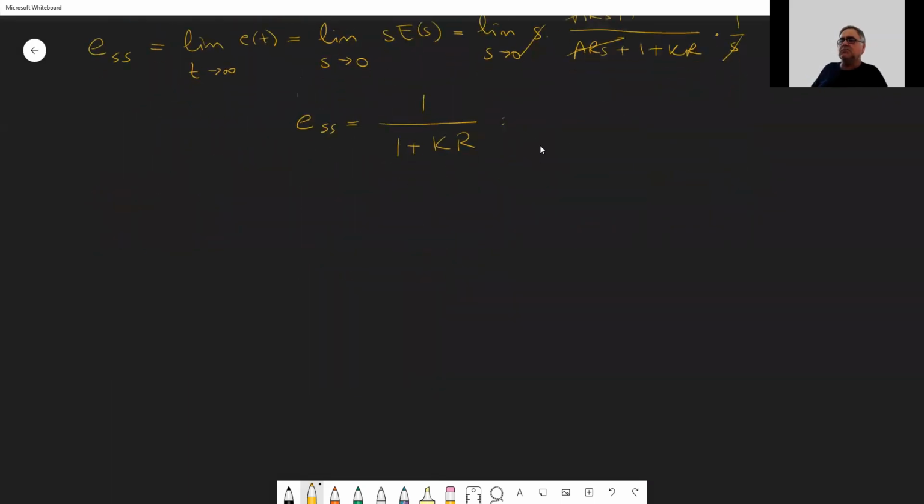So this control system, if you want to increase the height of the water in the tank, even if there is no disturbance, does the following. Let's say you increase it by about 1 unit, but what you can reach is something like this, and this will be your steady state error.